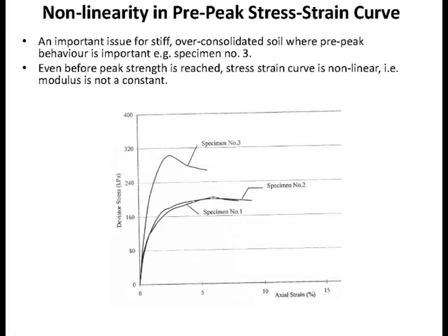If you have a material that looks like that, then the important thing obviously is to make sure this part is accurate and to make sure your stress doesn't exceed a certain percentage of the peak. Now this is where the weakness of the Cam clay is. The weakness of the Cam clay is that this part is completely lousy. This part is very poorly modeled. And so that's the reason why people say, for over-consolidated soil, don't use Cam clay.